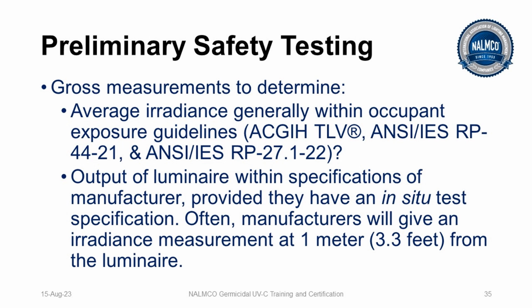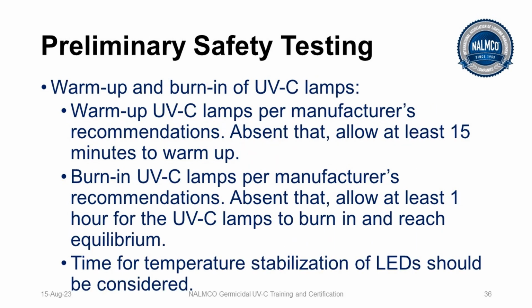I initially take gross measurements to determine average irradiance, generally within occupant exposure guidelines. The output of the luminaire should be within specifications of the manufacturer and provided by an in situ test specification. Often manufacturers will give an irradiance measurement at 1 meter or 3.3 feet from the luminaire.